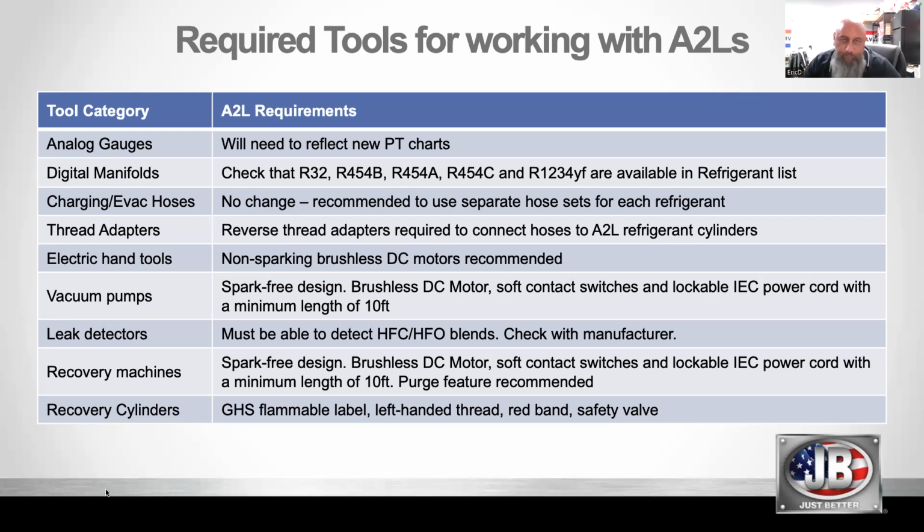No change in hoses, even though you're going to see people out there saying, oh, you need a special A2L hose that's branded A2L. That's just marketing. The rubber's the same. The brass is the same. The only thing that's going to change potentially is the left-handed thread, but on your standard hoses, I wouldn't bother. I'd just use an adapter. It doesn't make sense to have a hose with an A2L fitting on one side because you can only use it for one thing then. And even though we at JB sell those hoses, I would just recommend you go out and buy an adapter.